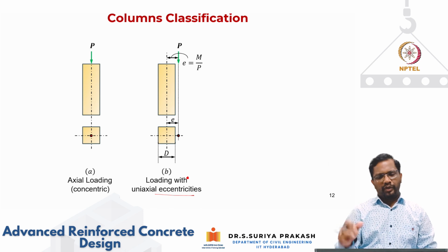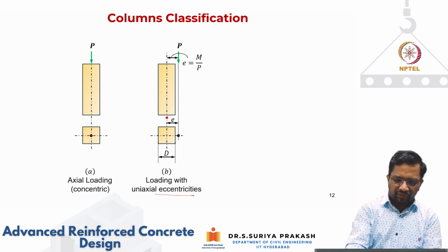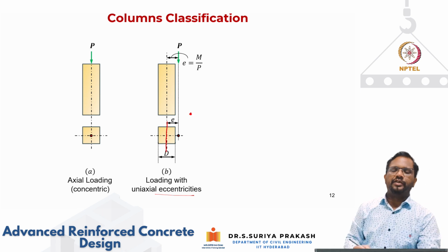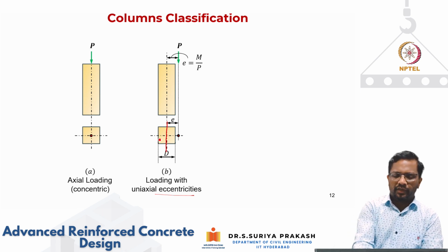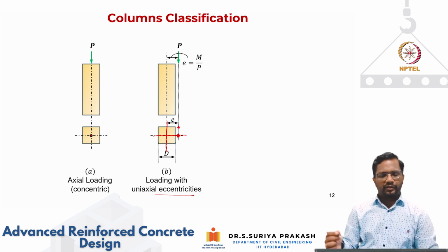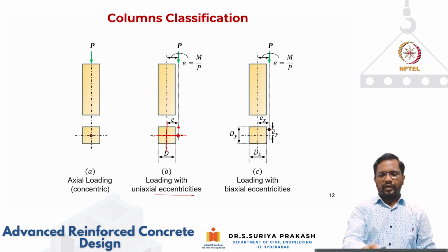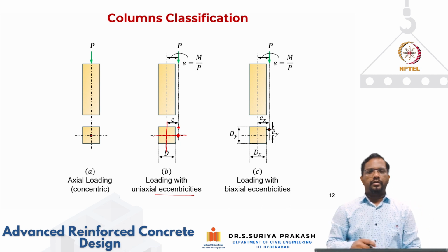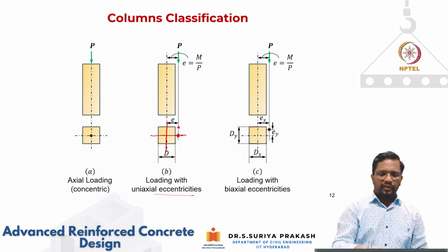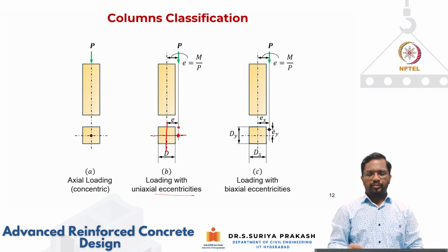However, the bending is only about this axis, because you have eccentricity with respect to only this axis. About the other axis, the load is along the axis, so there is no eccentricity. So again, you can design them for a combined bending and compression.